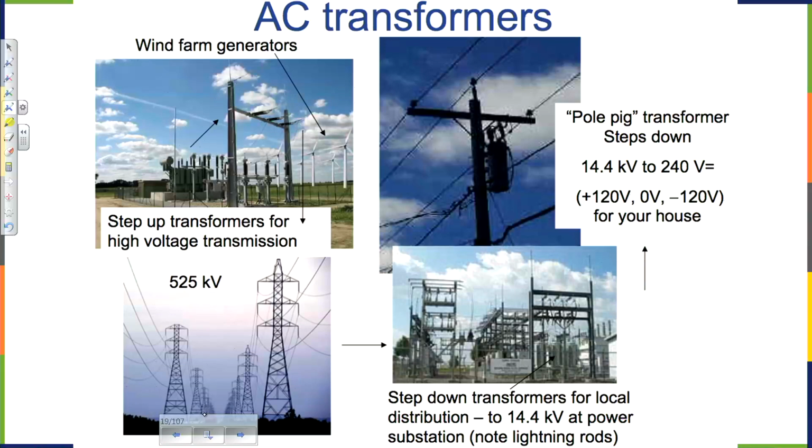The power plant generates very, very high voltage, megavolts. And then we use a series of transformers gradually. First, we actually jump it to even higher voltage to decrease current, to minimize the loss to thermal, to heat. But then gradually we go back through a set of step-down transformers to eventually 120 volts, RMS.